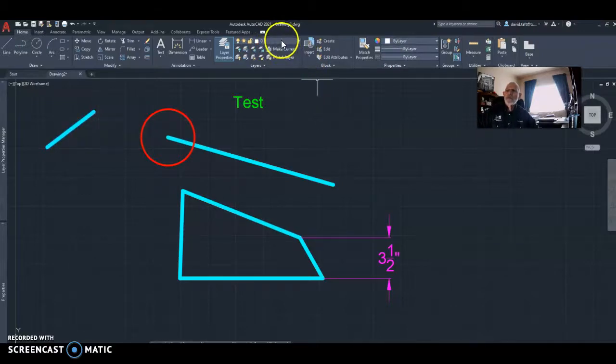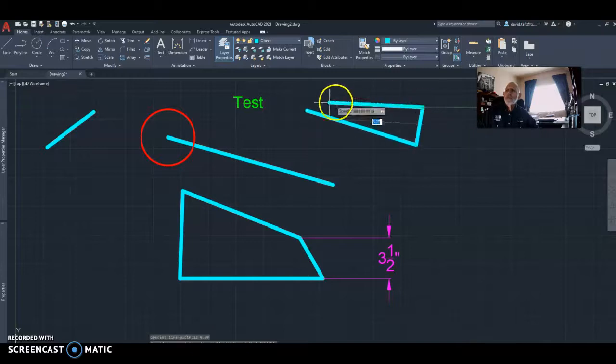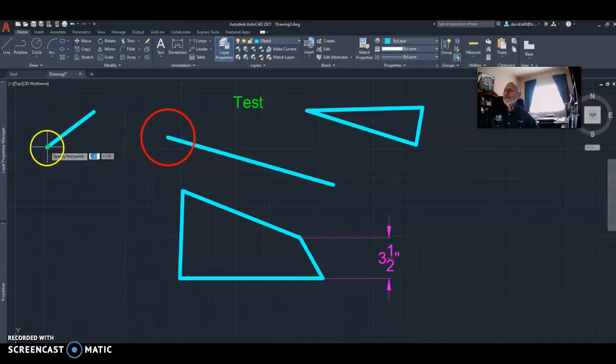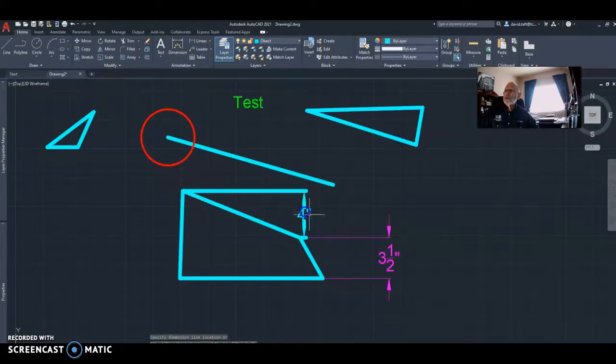So it's no big deal if you forget to switch layers. Let's say I was on the object layer and I was doing a bunch of work and putting things on the object layer, and I went over and did regular line work and maybe connected some stuff, and I said, oh, you know what, I need a dimension. I went ahead and went to dimensions immediately, and I go, wow, that one is on the wrong layer. Man, that looks terrible. But all I have to do is either do a match properties from one that's in here, or if I don't have one, select it, do the drop down, and then go to the dims, and that will modify that as well.